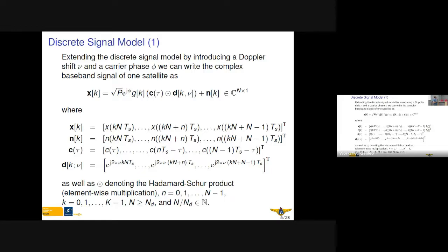in this model. So, okay, the new stuff here is the Doppler frequency, which is a complex vector, and the phase, which is also a complex number here. All this other stuff, g of k is real, it is minus 1, 0, 1. c is also real, delayed by tau. And p is also real, and also now the noise is complex, and before it was real.